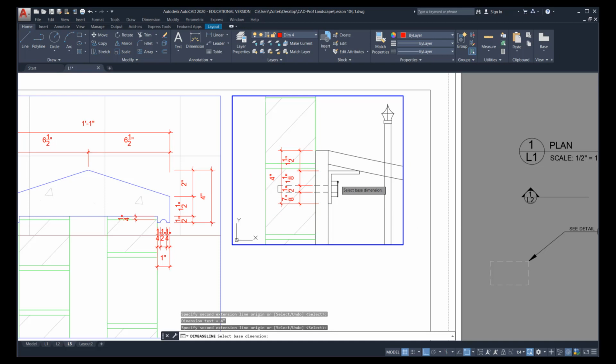Now arguably this is all interfering with the drawing. I could leave it as is, as it printed out. The print's in color, so it comes out nicely. If I don't like this, I can move it all. So I select move, and I click on all the dimensions. Now I'm in the viewport, so I can't use crossing because I'll actually pick up the brickwork. So I've selected everything, press enter.